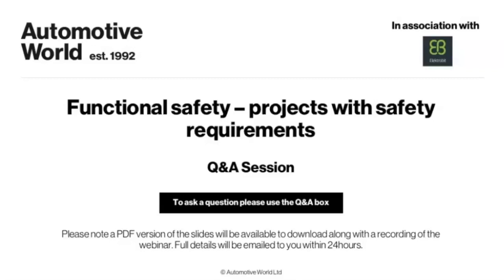to do a redundant system. And I think there's a lot you could learn from the avionics industry, because they actually used to do fail operational systems which are highly redundant, also with voters, to take a decision based on multiple inputs. But technically it is handled as two different binaries, and you could use our products also on the two different micros.